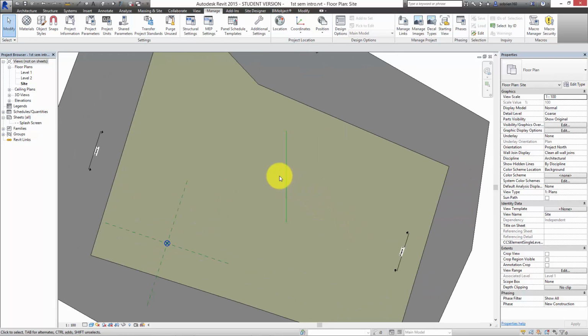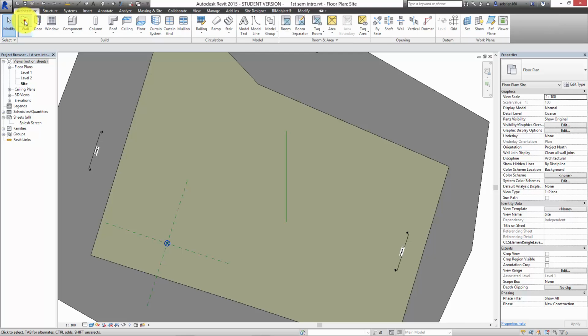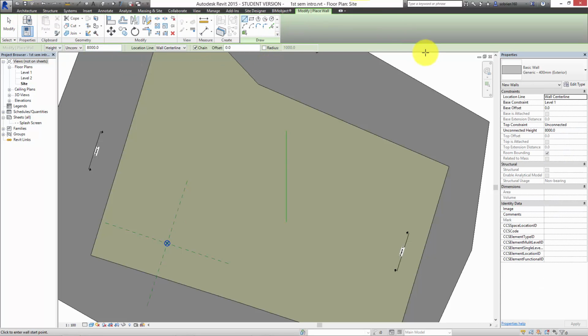So now we can start drawing up the project here. So I'm going to use the measurements that we have, and let's just try to see which way it is. So it's 9 meters long to start with, 3 meters wide, and anyway, let's just start doing it. So I'm going to go to architecture, and I'm going to go to wall. And what you get when you start, first of all, is a basic generic wall selected as the option. You basically use this for all your design situation, for your concept, until you get into the detailed drawing like you're doing there with Alan. So this is just to set up the rooms in general.